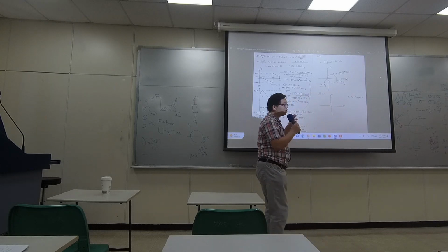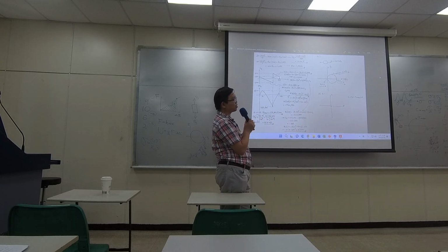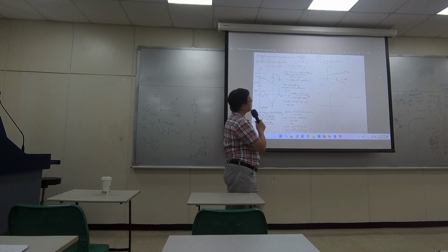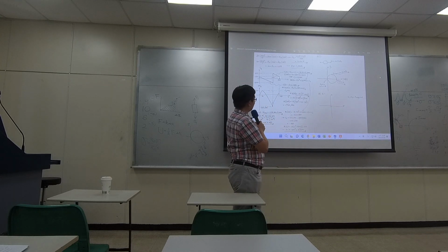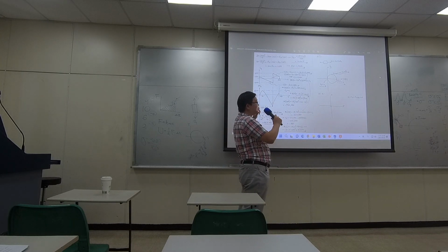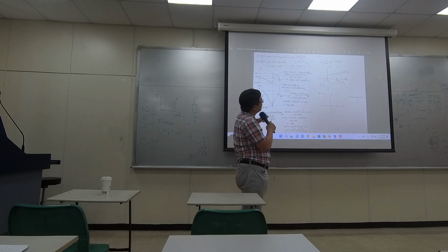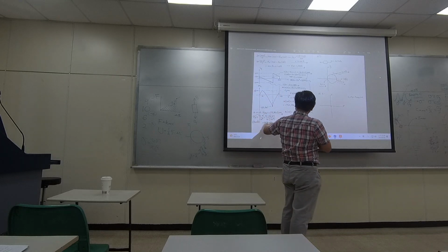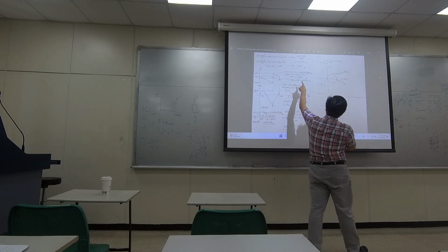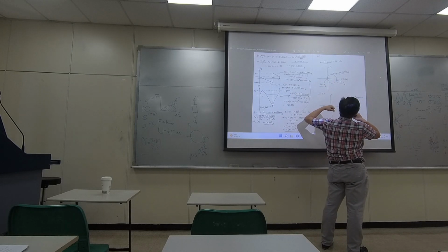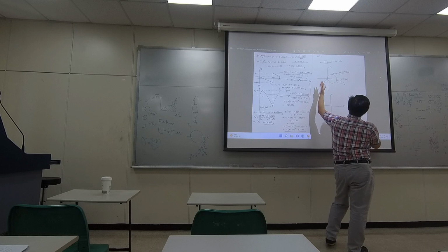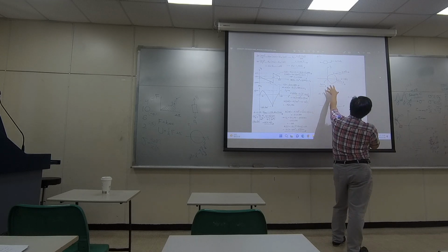It's a shaft with pure bending. There's no torsion, right? And we don't have forces along different directions. So it's purely bent. At that worst-case position, this material is being pulled from left to right. So it's just like a tensile test. So the Mohr circle is so easy. It's like this. Okay.